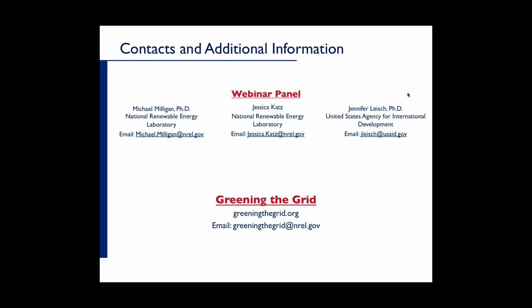And then I think the last operational thing is to take advantage of the fact that you can squeeze a lot of flexibility out of wind plants and solar, particularly central solar. I mentioned some of the possible difficulties with distributed solar. We don't want to do a lot of curtailing of wind and solar, obviously, because that's going to limit the objective, which is to reduce emissions. But on the other hand, there's a lot of flexibility that can be obtained from the renewable sources themselves. And I think that's a fairly new and pretty innovative thing.